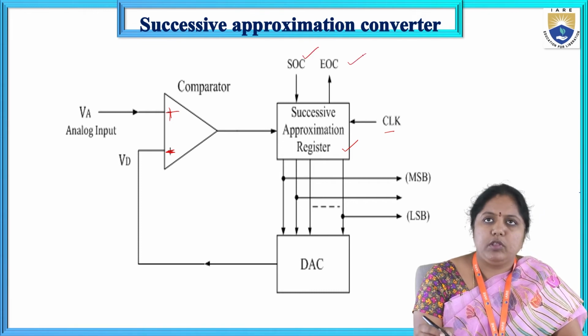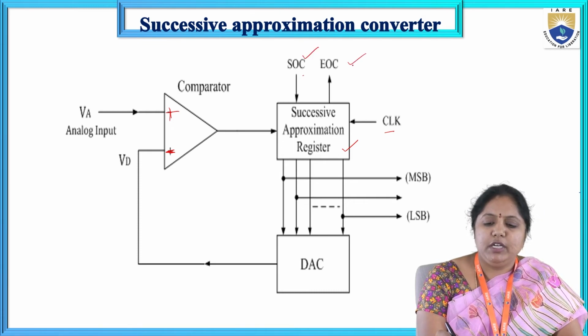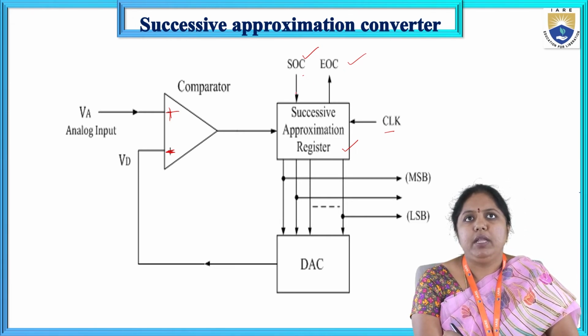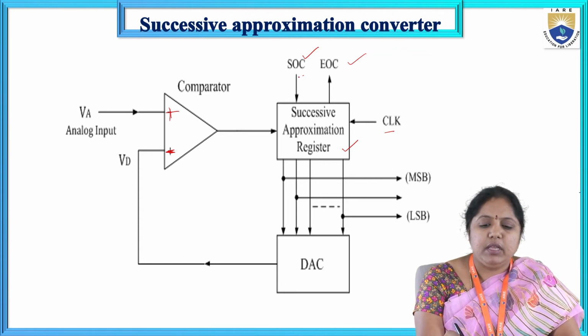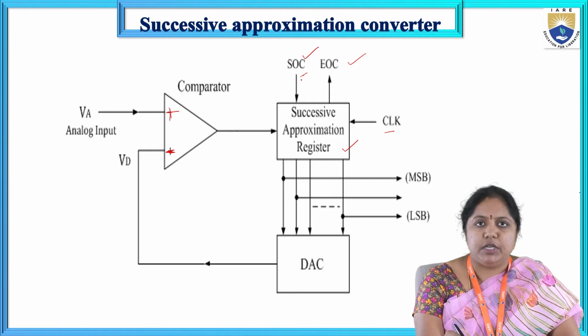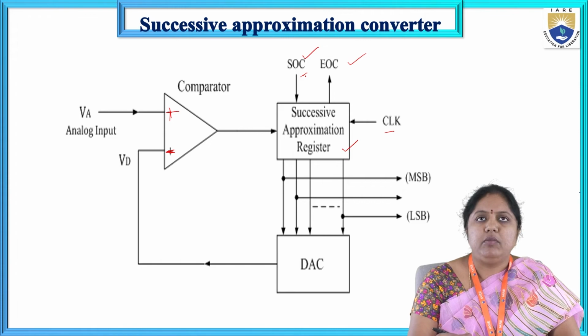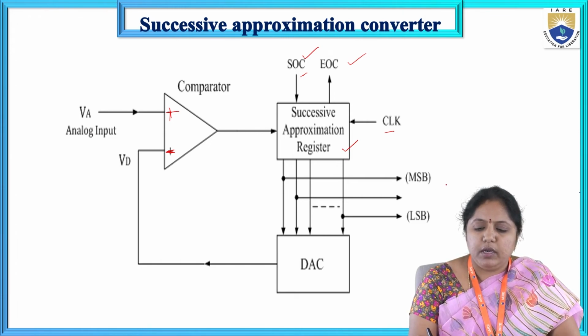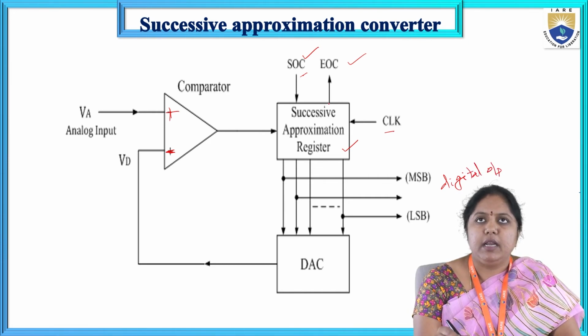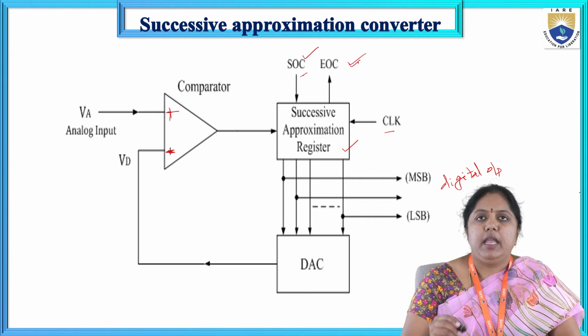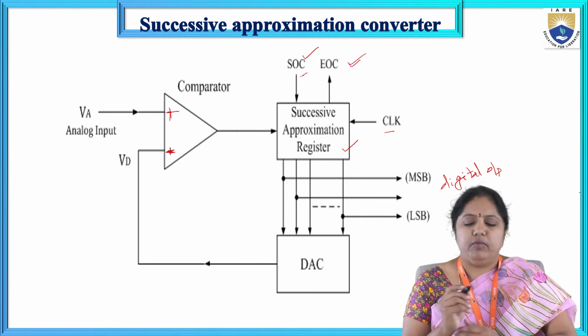SOC and EOC are there. That is start of conversion and end of conversion. Start of conversion means, before giving the analog input signal, I will switch on the start of conversion, right? Once the process of converting the analog input to the corresponding digital output is over, then automatically your circuit will activate the end of conversion. End of conversion.